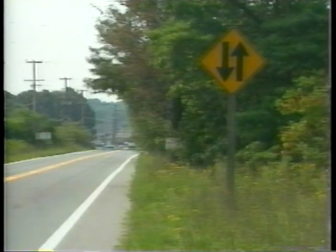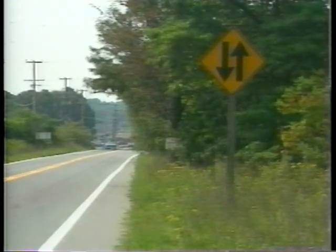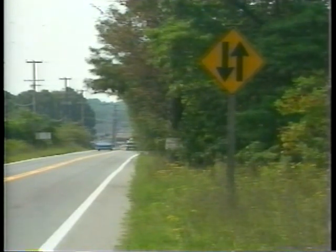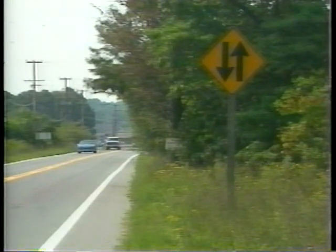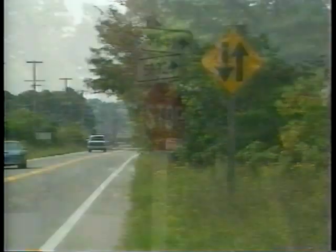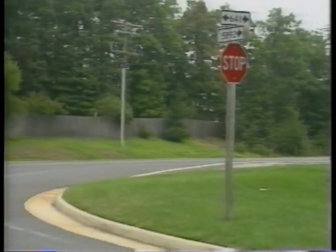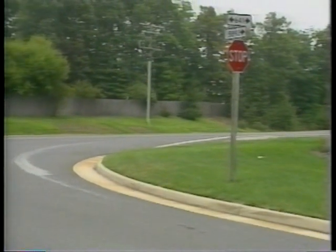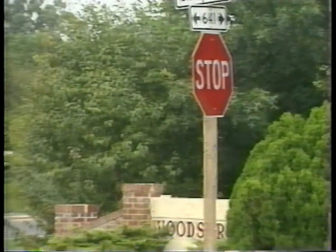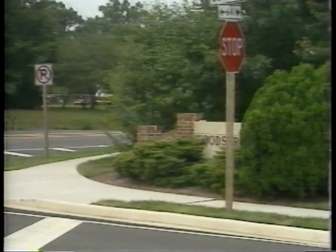Lateral clearance. There should be maximum practical lateral clearance to protect drivers who may leave the road and hit a sign support. The recommended distance from the road is 1.8 to 3.6 meters. In both urban and rural settings, the most important signs at an intersection are stop and yield signs. A stop sign should be put at the point where the vehicle is to stop or as near to there as possible.